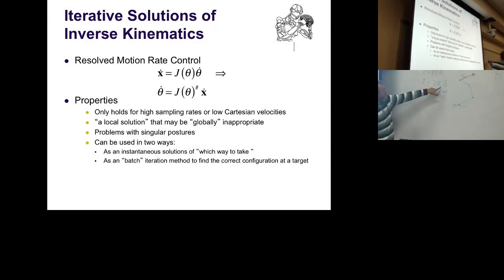In general, if you now want to solve for theta dot, now we're connecting a little bit to your homework. We get J minus 1. Actually, to be proper, let's call it J hash times x dot, where this is some kind of an inverse. And people like to use hash or daggers, which simply means it's most likely not a simple inverse operator. If I had a two-joint arm, then I have a 2D space which relates to a 2 degree of freedom joint space. It would be a square matrix, and the inverse would be fine. Now we're connecting to questions on the homework. This is something which I can normally invert, unless there are some algebraic problems with a 2x2 matrix, and I get a simple inverse.